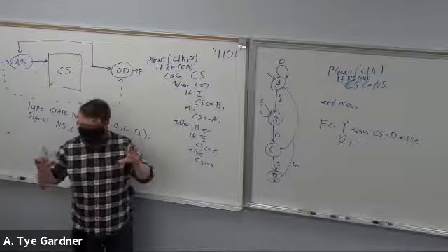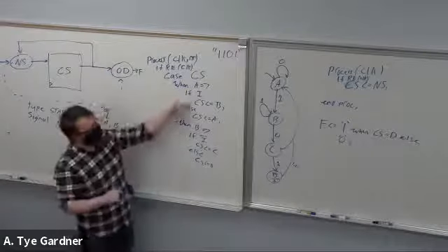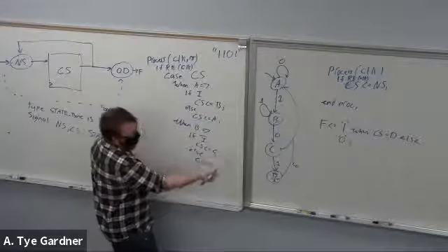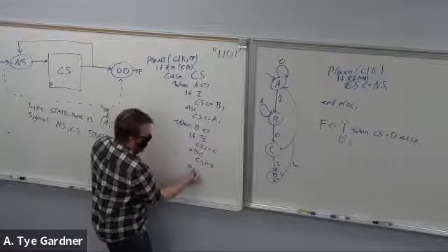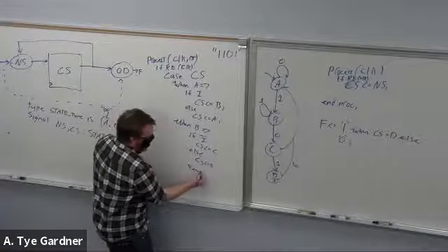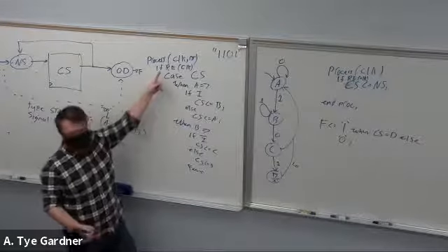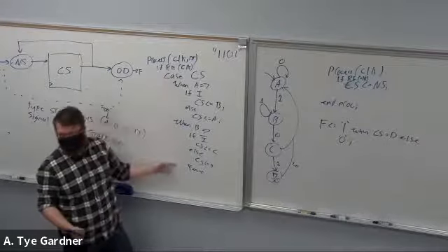your timing diagram, your waveform in your simulation, will show your current state as B. And let's say that I had some output decoder in here, which I'll get to in a bit, that says F equals 1. Well, what could happen is on this rising edge of the clock, I update my current state to B, but F isn't 1, right? Because I'm not in this case yet. I will be when the next rising edge of the clock happens, but I'm not there yet. So be aware, that's the one downside to this method.